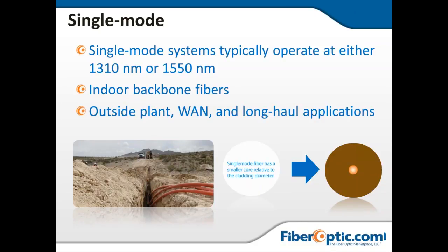Single mode, to represent the fact that single mode is going to be for long haul applications. Seeing much more single mode applications in the premise environments as well, between buildings and even on campus now. For a long time that wasn't the case just because the cost of single mode was so much more expensive. The LEDs that we use to launch into a multi-mode fiber were a lot less expensive than the single mode transmitters and receivers. So there was some advantage and cost savings on the short haul to use multi-mode.